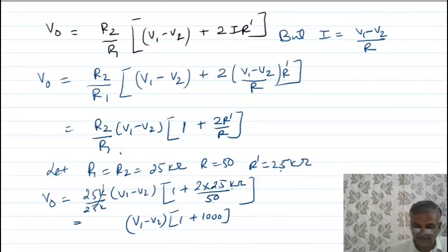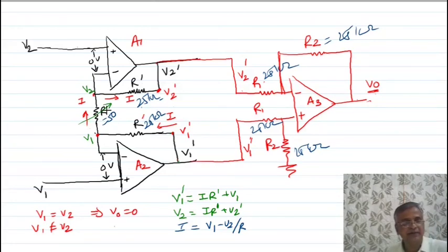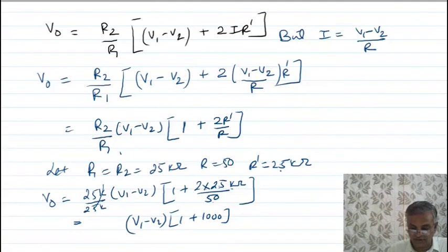So look here, let me show the variable circuit. I am giving the potentiometer to change the gain of the amplifier. But by mistake, if you are making R 0 by changing the pot position, if R becomes 0, then look here what will happen. If R becomes 0, then this term becomes infinite. So your gain becomes infinite.